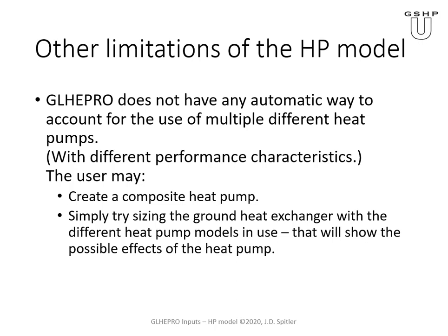It just simply has the possibility of having loads on a heat pump with one set of curves for the heat pump and then loads directly on the ground heat exchanger. And by the way, that is an alternative. If you really feel that you have a complex situation that you need to account for, you can develop a model independently, or you could calculate, assuming a set of temperatures coming back from the ground, the heat rejection rate over various time periods, and then you could specify those loads as direct.